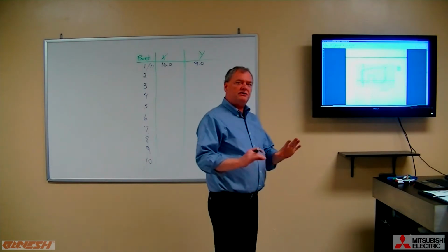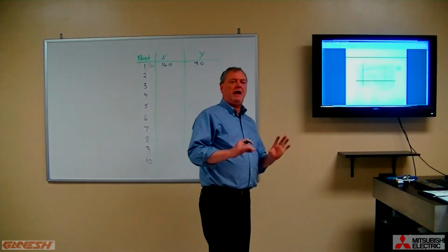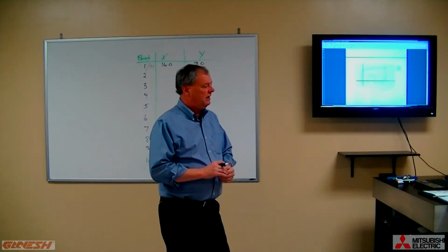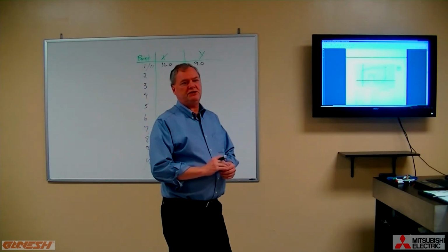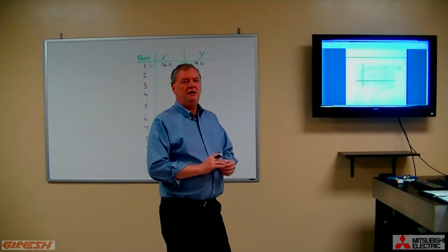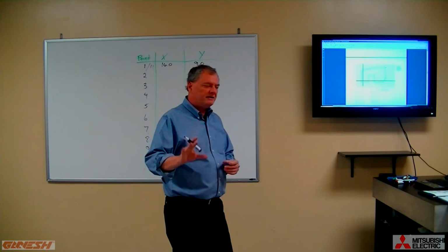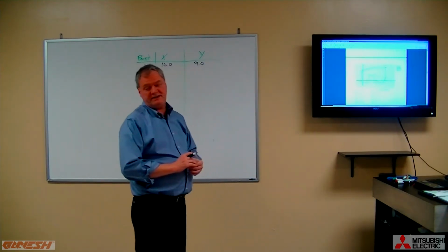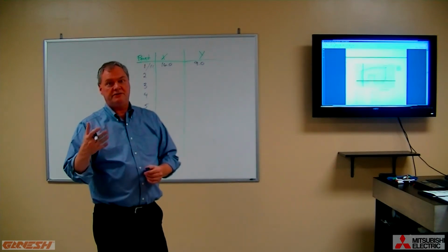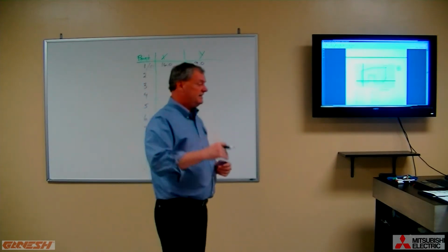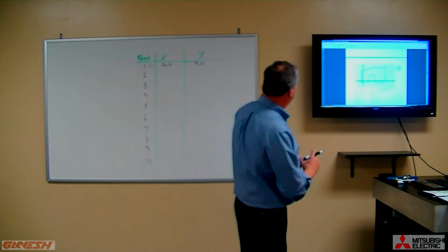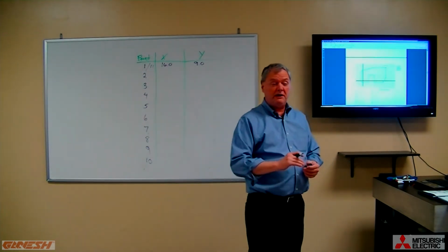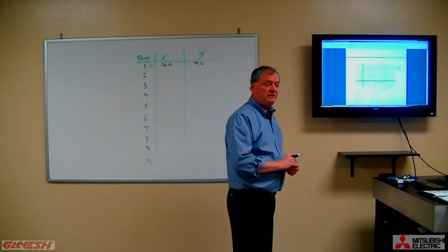At the very least, you should consider making it a habit to use decimal points, because as you're programming on the machine, most machine tools, the control will require a decimal point. Otherwise, it will interpret the number 16, for example, as 0.0016 instead of 16. So now we'll start adding decimal points for clarity, and stay with that convention as we